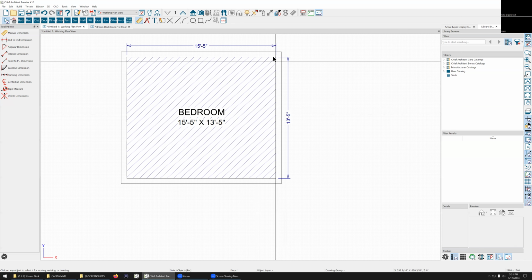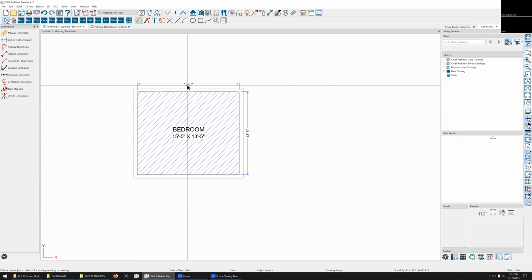It would be nice if the user could set the room up the way you want, but also it's going to look at this number and it's going to know the IRC and it'll know the joist span. So if you tell it, well, I'm going to go with 2x6s here, it'll immediately not let you because it's going to be conflicting with this number and the IRC. Correct. And then that way, as you drew it, it immediately put it to 2x8 because it knew it can't let you do 2x6. And that's prescriptive. That's data that doesn't change. That's in the code book.